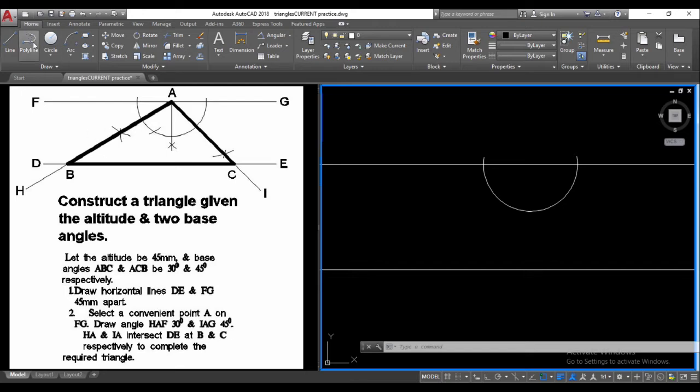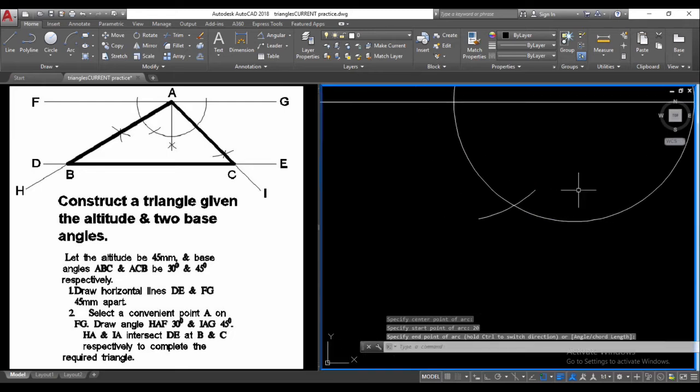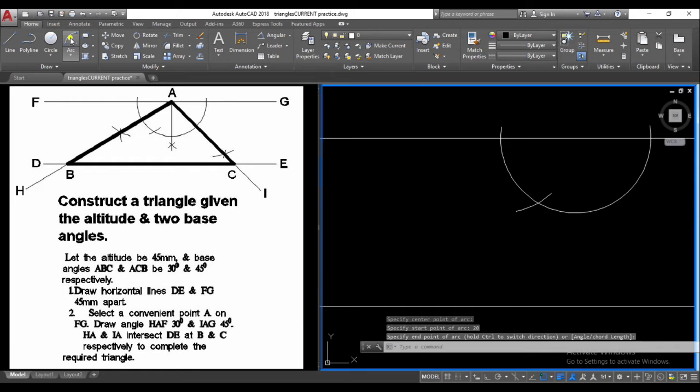and then we'll bisect it to get the 30 degrees. So our tool again, from this point, you should all know by now how to construct the 60 degree. You have to use the same radius, so we're using 20, enter, and we'll just get our first arc there. And now we have to repeat the arc tool again from this point, and we could use a different radius here.